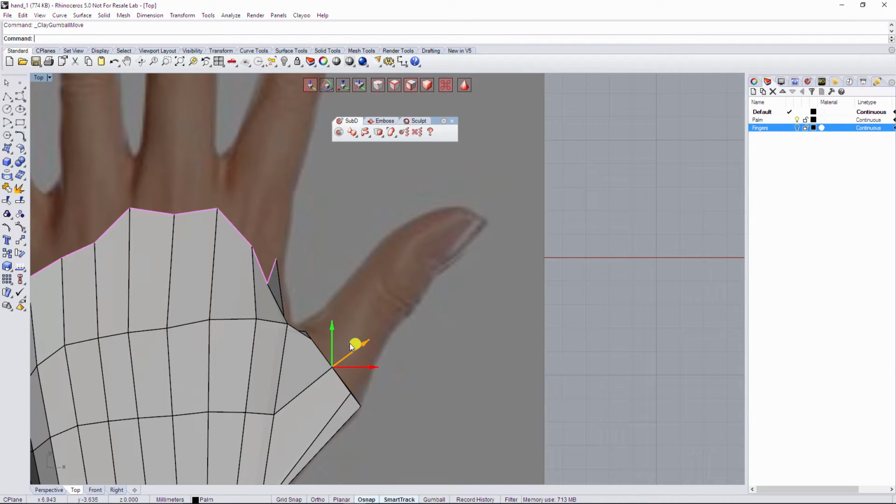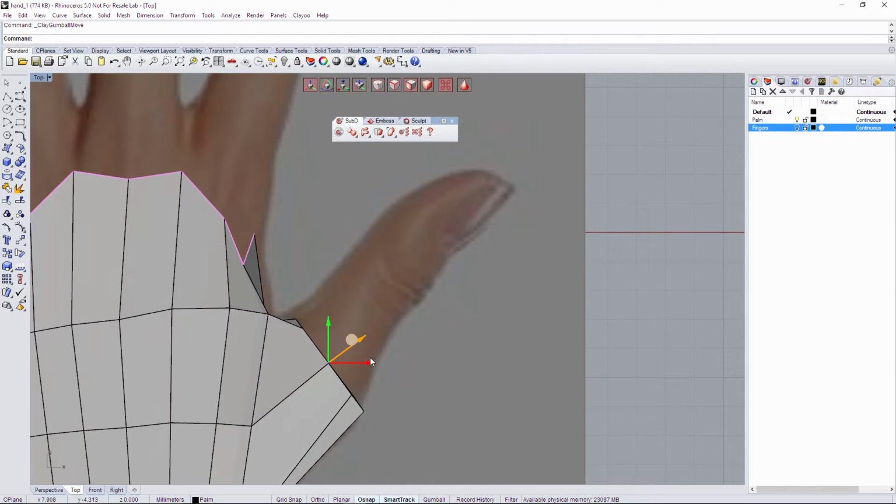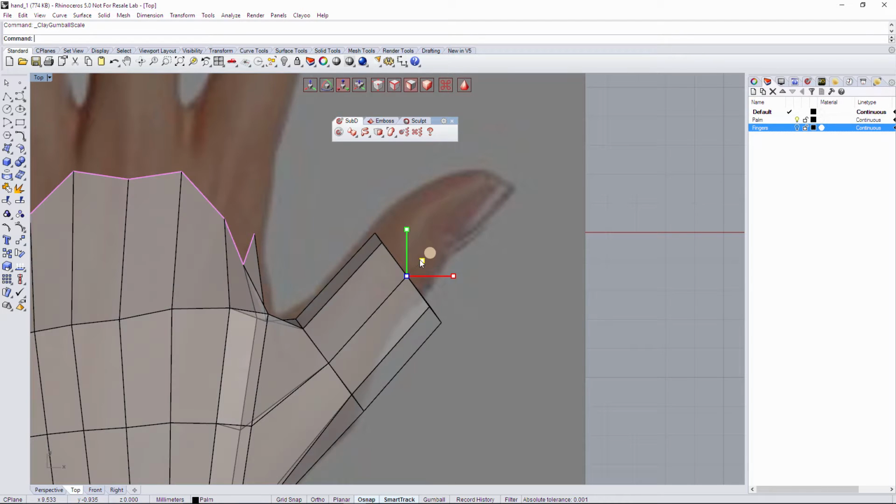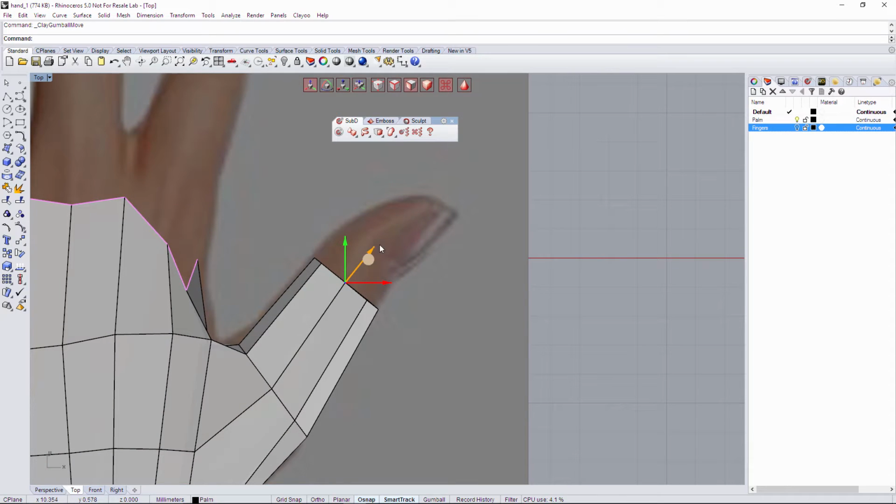So just rotating a little bit, and now we're gonna hold Alt to create the next extrusion for our thumb. Now clicking R for just rotating, scaling a little bit, sorry, just E for extruding, and again readjusting the placement of these faces, and also holding Alt, okay, to create another extrusion.